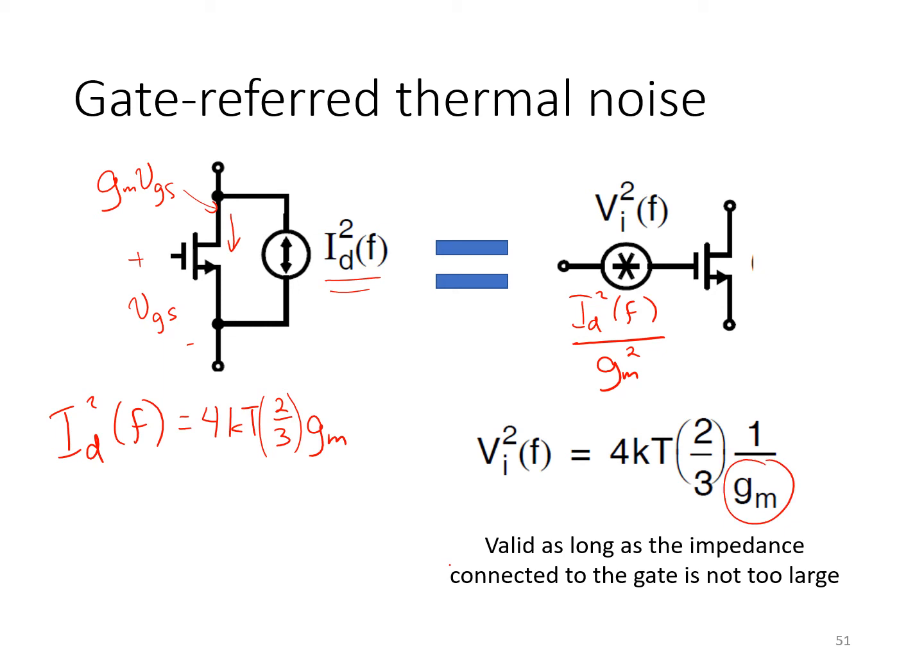That clearly emphasizes that in terms of the input referred noise that we would see appearing directly superimposed on our small signal VGS, we would actually like to increase gm, and that would in fact give rise to a larger signal to noise ratio.